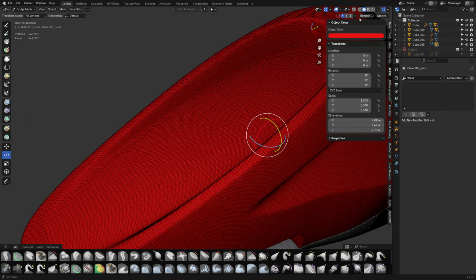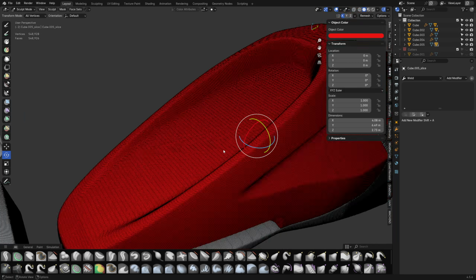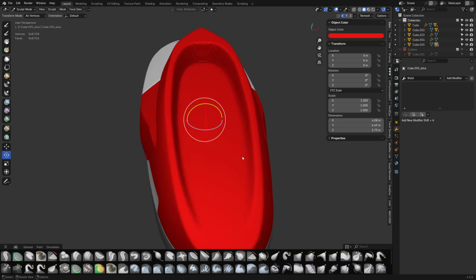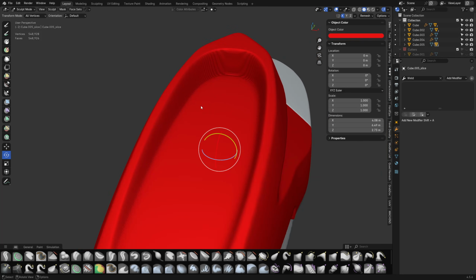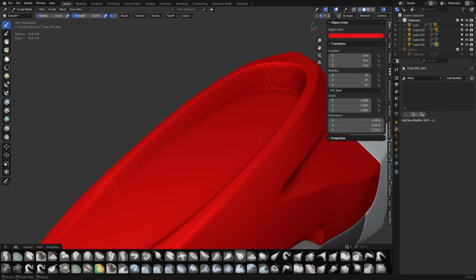You have to change the resolution each time. If you use the exact same resolution, you're going to develop little dots all over your model. It doesn't look that good. But there's all kinds of different ways you could possibly approach fixing this little issue here, like using mesh filter and stuff like that. I think just the regular smooth tool, low strength, right? I think this works pretty well, personally, but you got to stay inside the lines, okay? You can smooth the lines out later with the mesh filter if you need to. Just very light strength, go through, get it going.